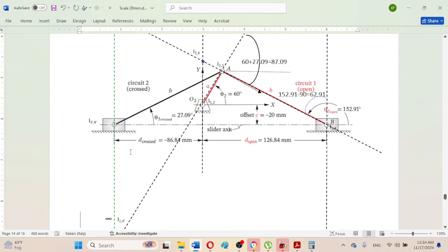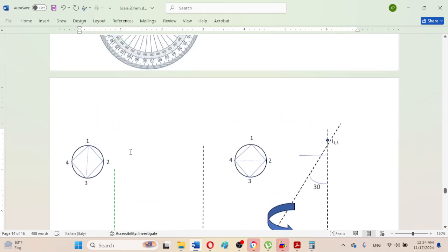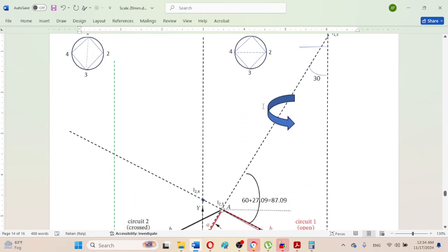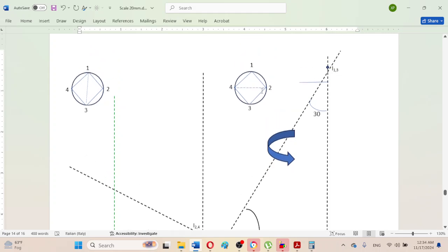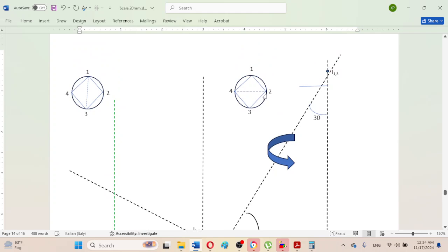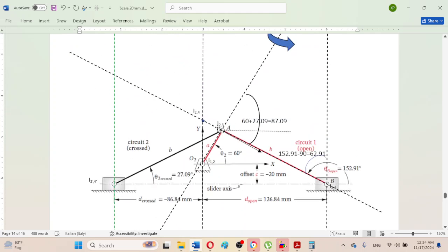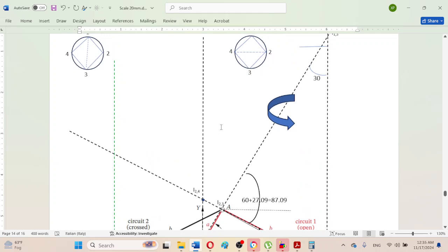Now the sixth instant center can also be located. So use this linear graph. In a similar manner, use this lower triangle, for example. The instant center 2, 4 will be located on the line connecting the instant center 2, 3 and instant center 3, 4, according to Kennedy's theorem. So let us see, this is instant center 2, 3.